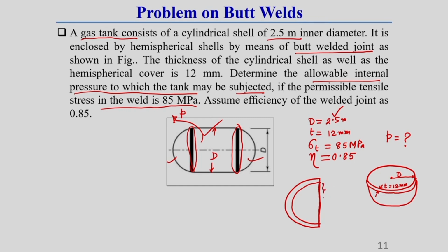Now, you see this internal zone will generally create a pressure projection, that is, if we take the projected area of this hemisphere, how the pressure will act. So, the pressure will act on this projected area like this, correct. Due to this pressure, whatever force develops, this pressure force, is generally the pressure P, which is acting along this projected area of this hemisphere welding zone region.